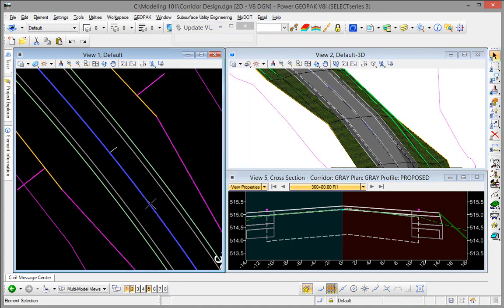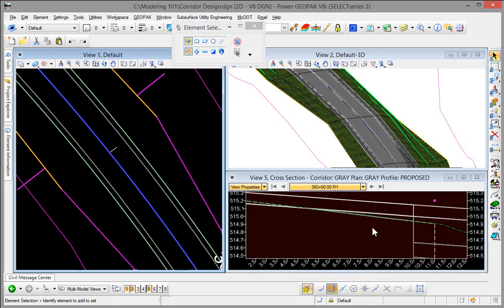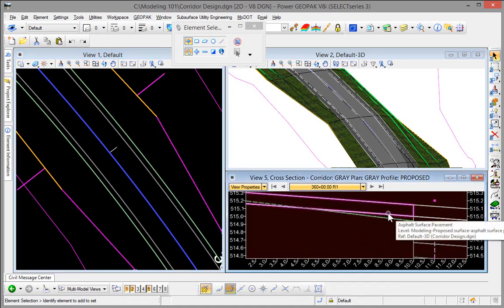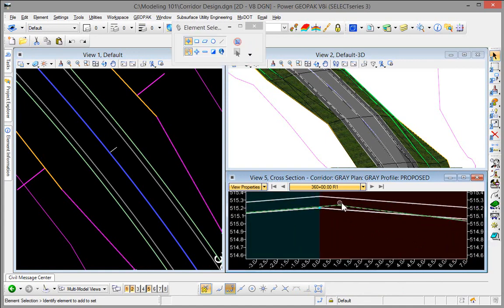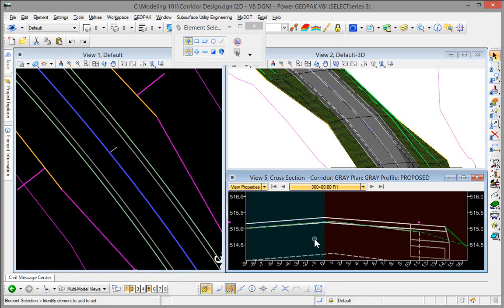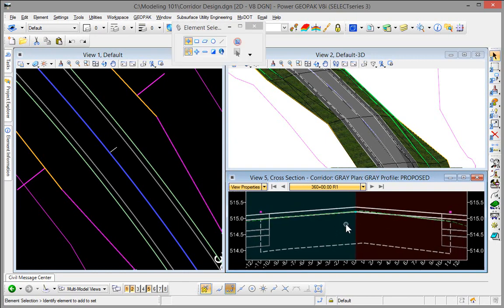And what we did here is we purposely started our widening inside of our existing edge of pavement by about 6 inches, because that allows us to easily clean off that edge in construction that may or may not be true. And so you take a look here, we have our proposed aggregate surface, but we also are going to have a section in here, and you can see right there, of our leveling course that takes place. And then over in this area, we're going to have some binder, leveling binder that's going to be taking place where we're cutting into that existing pavement, or cold milling. That's going to be milled out and taking into account that we mill out that particular section.